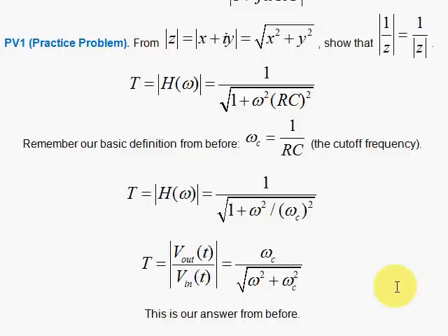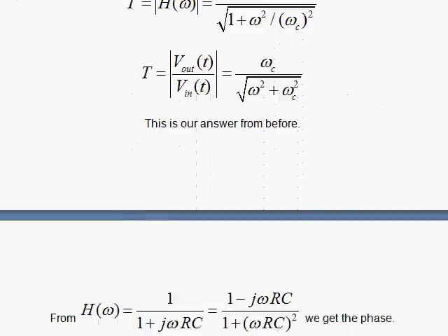And look at that. A simple phasor setup using the concept of impedance, really. The ratio of the impedance across the capacitor over the total impedance is all you have to do. Really didn't need phasors even when you come to think of it, although the phasor language is built in with these impedances as we showed in the previous video.